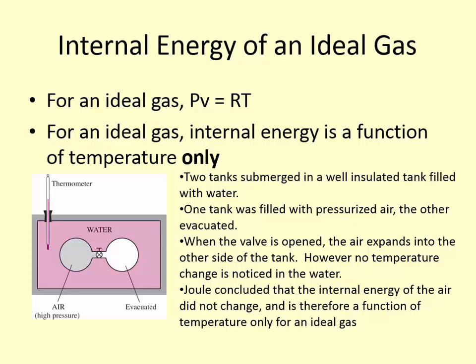We've already seen that internal energy is not just a function of temperature for water or for R134A, because we've used the property tables and we can look at how it changes under the dome. So even if we're operating at a constant pressure and a constant temperature, our internal energy changes from one side of the dome to another. So undergoing a phase change is not a constant internal energy process. There's a significant energy change there.